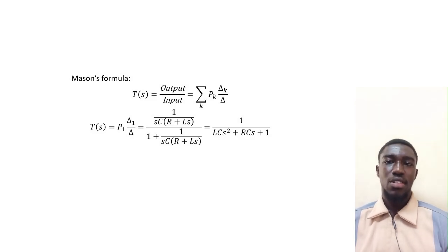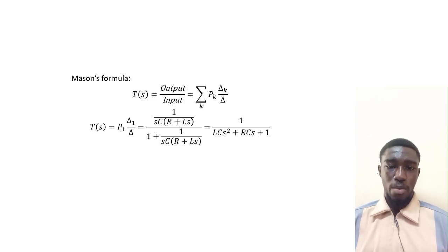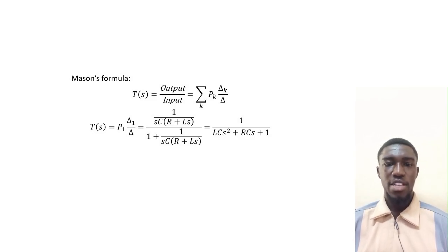Since my colleagues have already explained both methods, I'll focus purely on comparing them. The first method, voltage divider rule. This is quick and intuitive for simple series circuits like this RLC circuit. It only works for passive circuits with clear series structure. The second method, signal flow graph. This is systematic and visual and shows signal paths and feedback loops clearly. It requires drawing the graph and using Mason's gain formula.